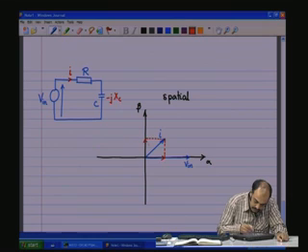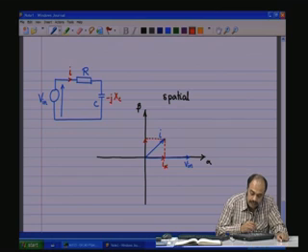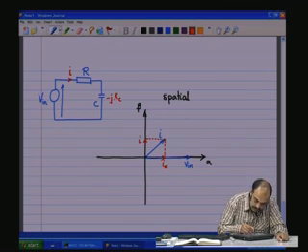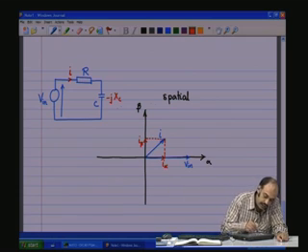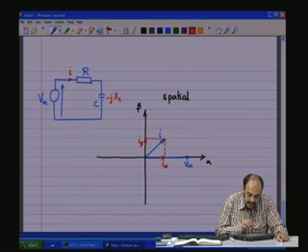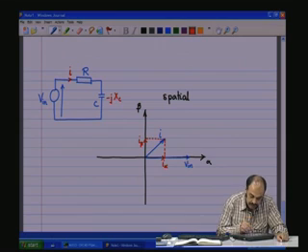which is in phase. So, we call that one, let us say, I alpha, and there is another component which is 90 degrees phase shifted with respect to V in, and we call that one, let us say, I beta. So, I alpha is the in phase component of V in, and I beta is the component of the current which is 90 degrees or orthogonal to V in. Now, this whole unit is rotating at frequency omega, and this is a picture at an instant of time when V in is equal to 0. That is, the V in projection is equal to 0 on the temporal axis.